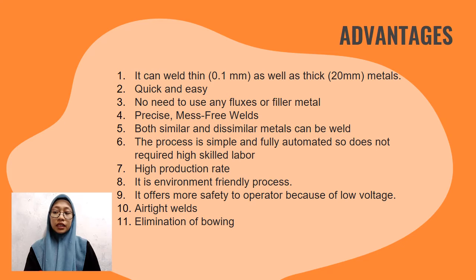When a workpiece is kept hot for too long, it can start to lose shape, bowing around the side of the weld. But resistance welding does not stay hot enough to bow because it can be done in a short time duration.